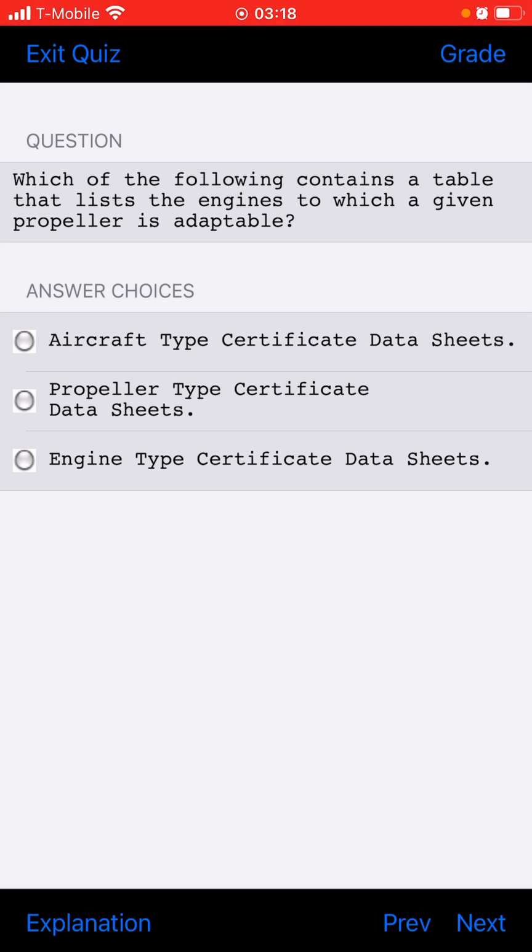2% of regulated voltage. The maximum allowable voltage drop between a generator and a bus bar is 2% of the regulated voltage.